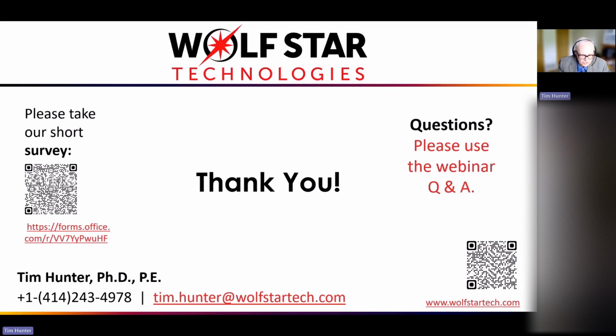Let's see, I got another question here. Is there a maximum number of loads or gauges? So the software has no built-in limits to it. Basically, we can handle any number of strain gauges, any number of loads, any size FEA model. The bigger things get, the slower things go. You know that. But really, we've done problems with 40, 50 loads and hundreds of strain gauges, and that's just fine. It all works fine with that.